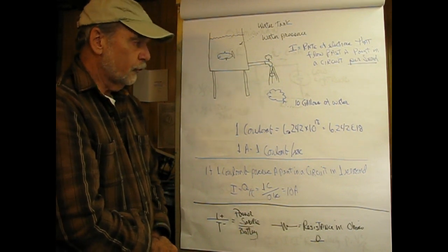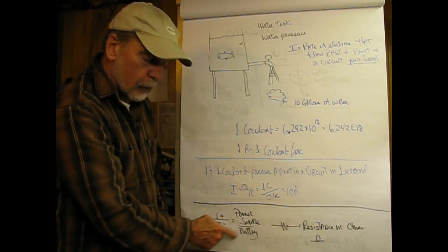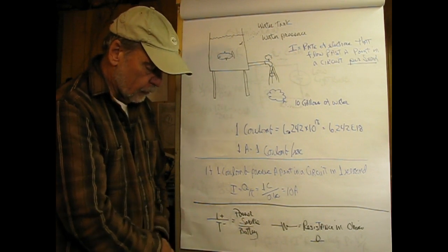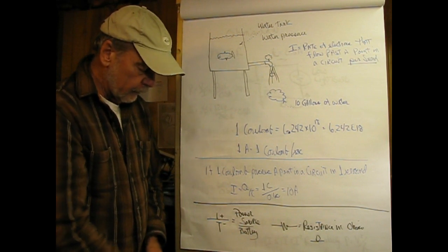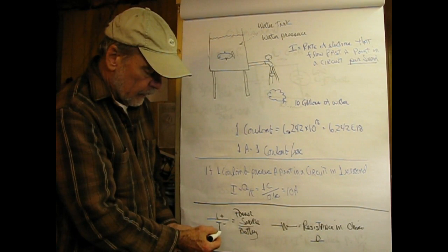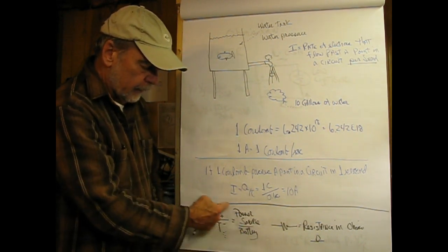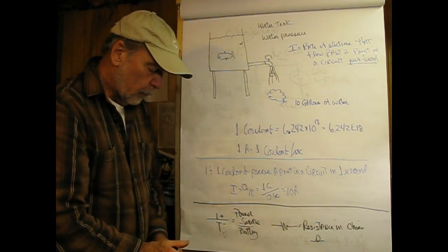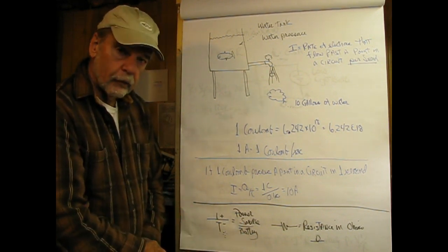Likewise, we have symbols for pressure in an electric circuit, and this is the symbol for a power source or a battery. The larger line here represents the positive side of the battery, and the smaller line represents the negative side of the battery. And as I said before, this stores chemical energy, and what we can see here is an excess of electrons, but they can't flow around unless there's a completed circuit path. So all batteries have an electrostatic potential even though no current is flowing.